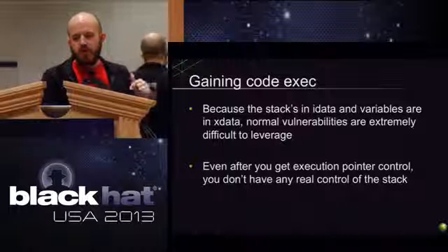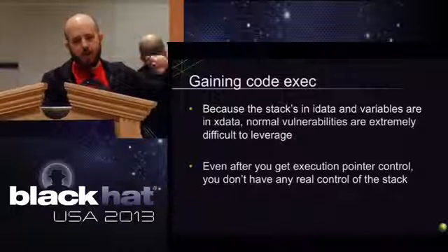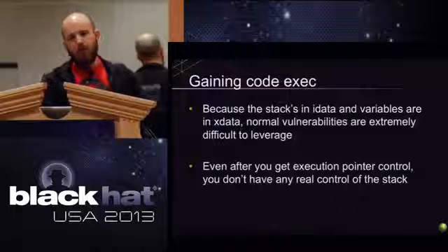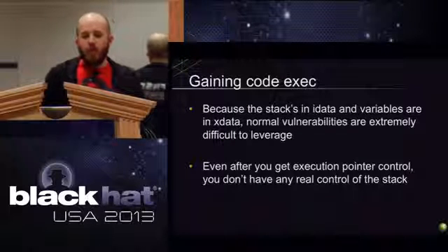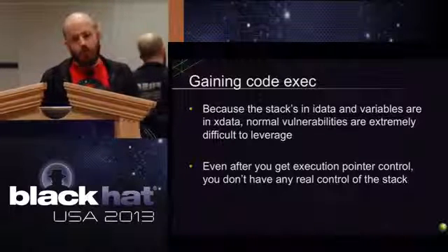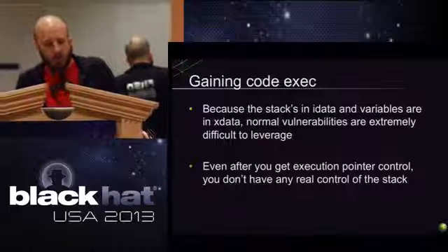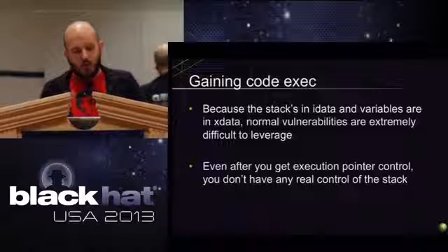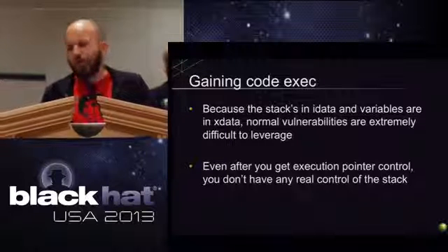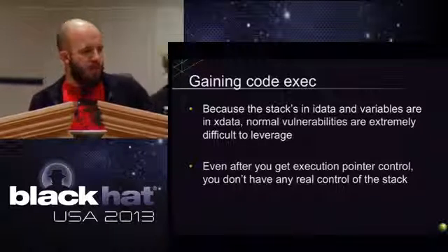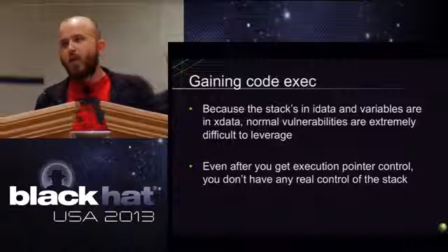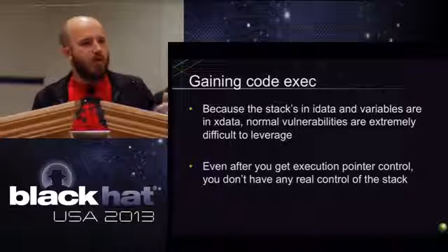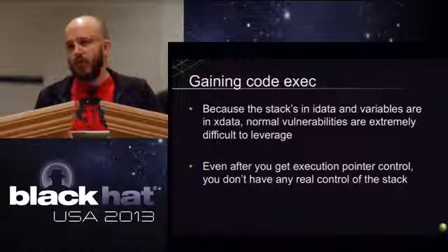Because the stack's over in iData, in the internal RAM, and variables are over in external data, normal vulnerabilities will not work, right? It's just incredibly hard to leverage those. And then, unfortunately, even after you gain execution pointer control, you still don't have control of the stack on this architecture. Because whatever mechanism you're going to use to gain execution flow is not coming through the stack, right? So you don't have control of that.